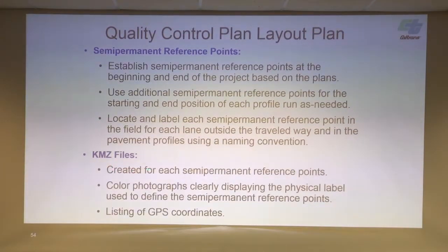KMZ files are also required to be submitted in this part of the quality control plan. A KMZ file is basically just a file that when you click on it, you can go to Google Earth and you'll see the coordinate information. We want them to take color photographs of these semi-permanent reference points that they've placed in the field. So anybody that pulls out to the job site has a better chance of making sure they find that semi-permanent reference point. And also GPS coordinates. With this KMZ file, you can also get GPS coordinates out of that.